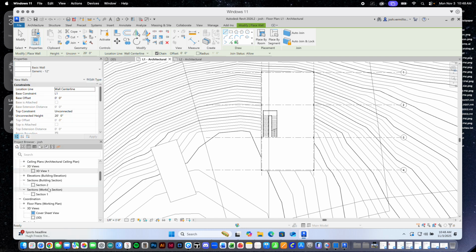Because what I want to do is make a super thick-looking wall that then turns and becomes super thick with the same thickness roof, and then comes back down and becomes the same thickness wall, right? So I'm basically making a frame around my window wall, and I want it to look like one continuous sort of folded surface that's thick, right? Has a certain thickness to it. And for whatever reason, I think when I was doing the roof, I picked something crazy, like 32 inches, 2 feet 8 inches. So I'm going to make my own custom generic wall that's 32 inches, right?